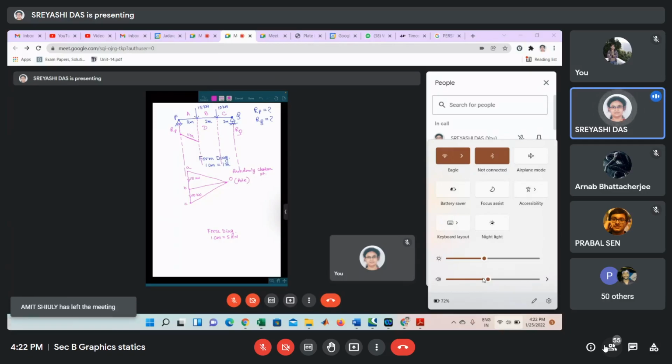Normally, we need to start this parallel drawing from the hinge joint. I am coming to why. But for this case, when all the loads are vertically downward, we can start at any point, just in the direction of the force. We know that the direction is vertically upward. So here we have drawn this line parallel to OA.